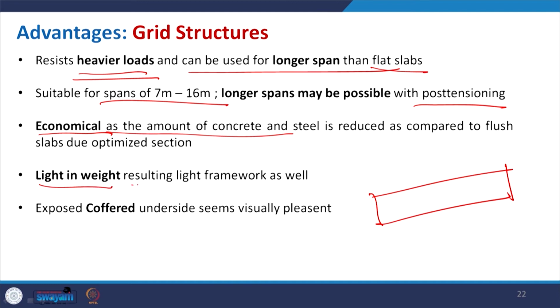It is light in weight, resulting in lighter framework. So, definitely when you reduce the cross section, this can effectively reduce the framework. The exposed waffle slab also looks visually pleasant, and we can put some lights so that it can create a nice environment from the interior.